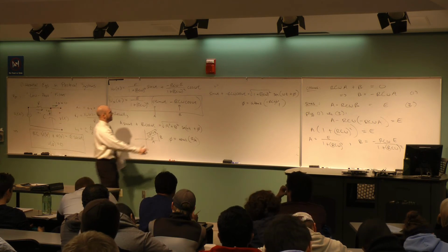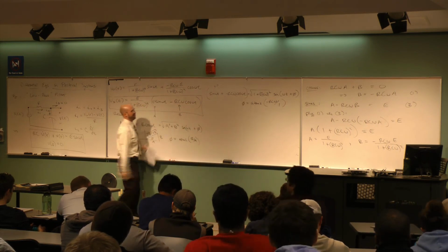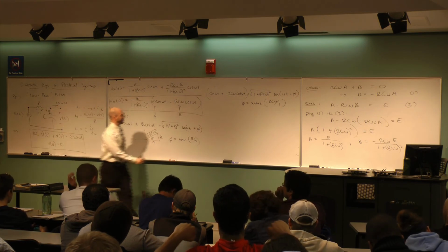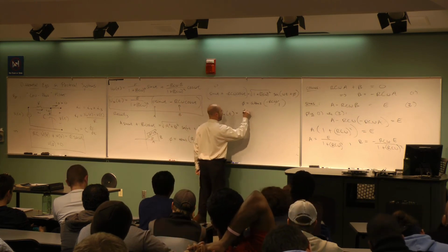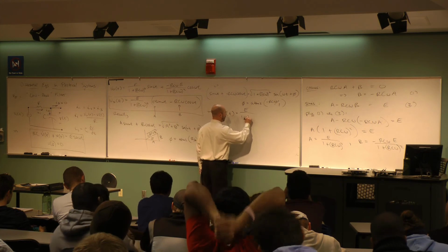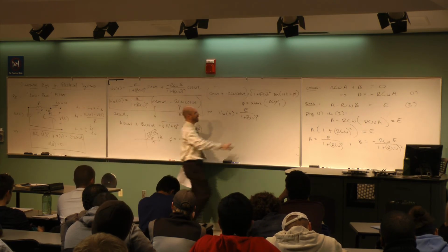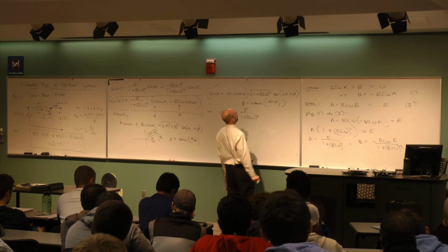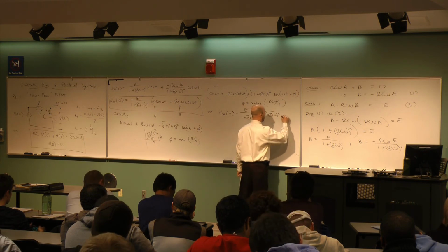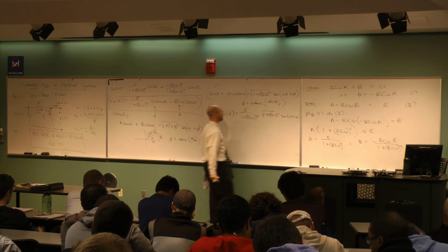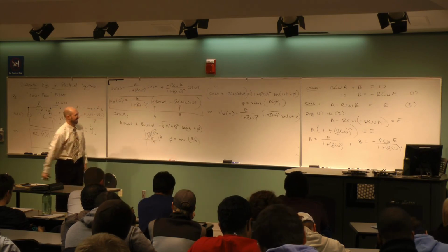So if that's true, then everything in the parentheses right here, to make it clear, this left-hand side is just this parentheses. We ought to be able to replace it with that, and make life a little easier to understand. V steady state of time is equal to E divided by 1 plus RC omega squared. And now we're going to multiply that by what's in the parentheses, which I have now combined into a single sinusoid. So it's the square root of 1 plus RC omega squared, times the sine omega t plus phi. And here's the neat thing about this. Can I simplify this even further?